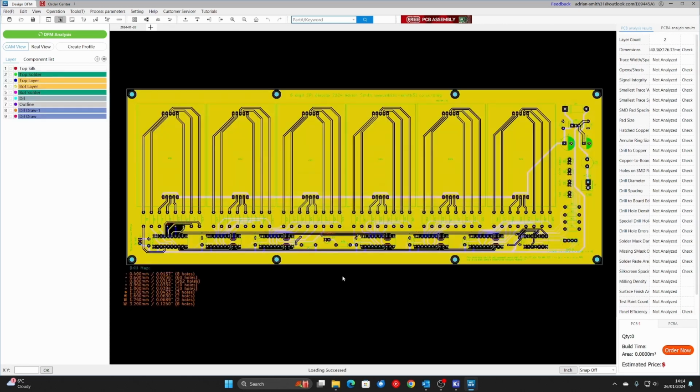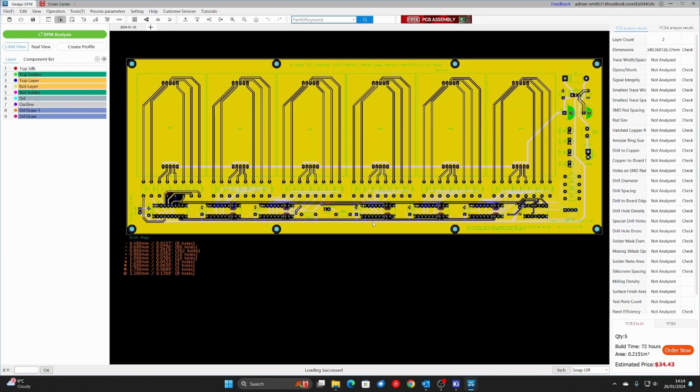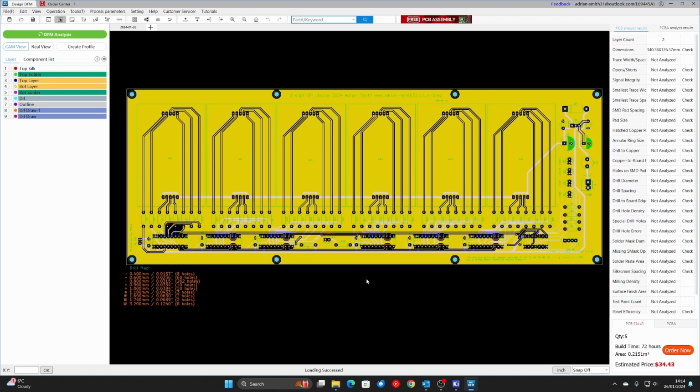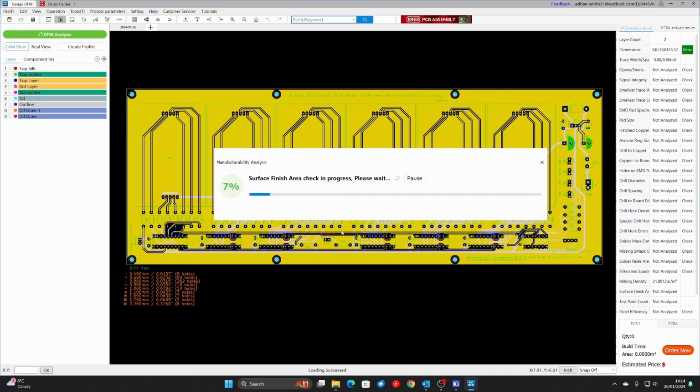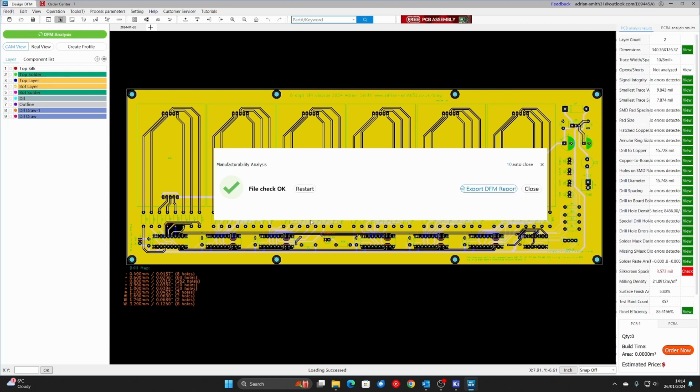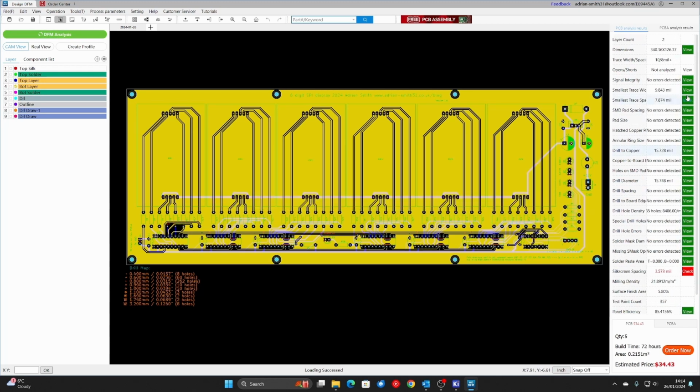and open it. Now, what this tool does, it's an ideal utility to run once you generate the Gerber files, just to finally check you haven't made any mistakes. It'll check your good design practices for circuit boards, make sure your trace lengths are all good, there's no bad signal integrity, anything like that. Once you've loaded your Gerber file, you just click on this, and then it will show you, if everything's all good, it will show you in green.